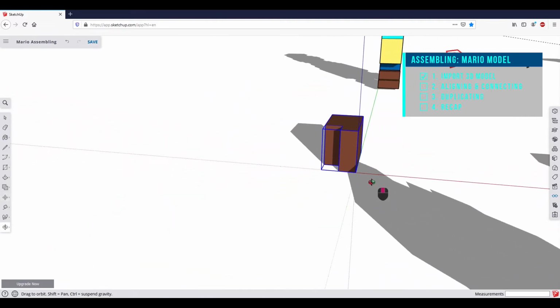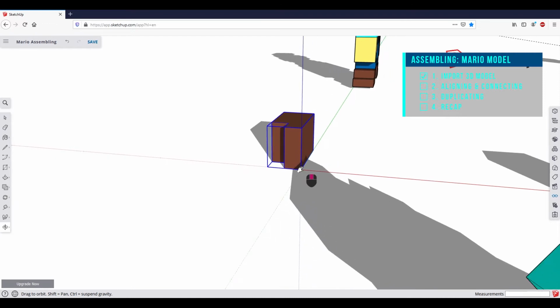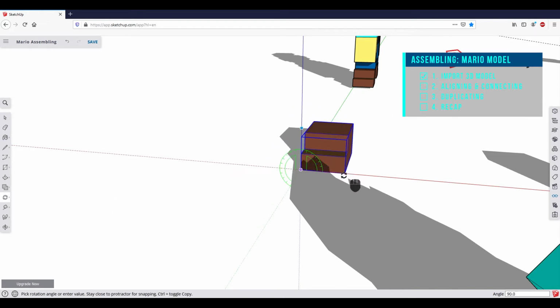To align the foot, we press the Q key for the Rotate tool and place it at this corner point along the green axis. We can align our view accordingly or press the left arrow key. In this exercise, we will always place the tool on the corner points of the object, not outside at the boundary box. This way, the objects can be aligned correctly.